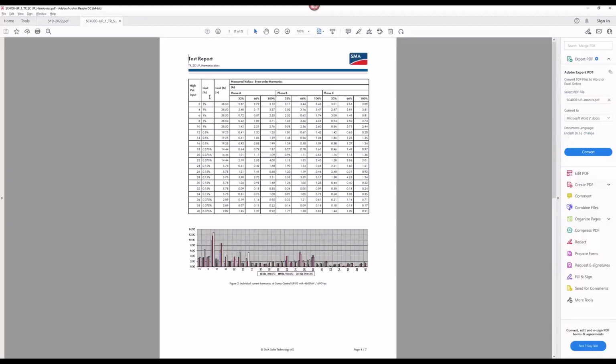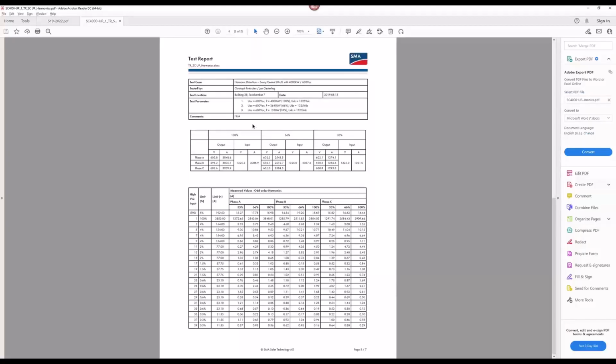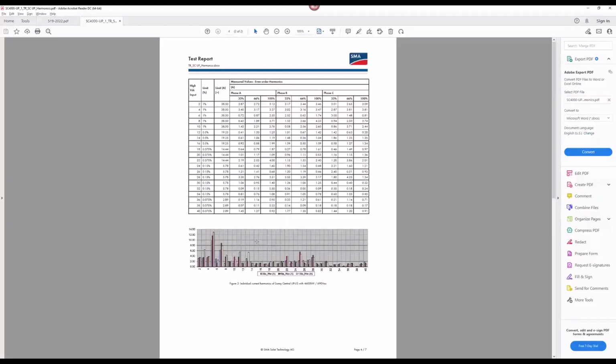what's your harmonic injection spectra, right? You can see that it looks exactly the same as what EasyPower would take as an input. What is your harmonic order? The second, 4, 6, 8. On the next page, you will see your harmonic current order as the third, 5th, 7th. So all even harmonics are in a different table.